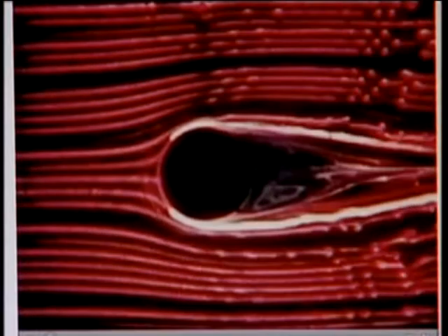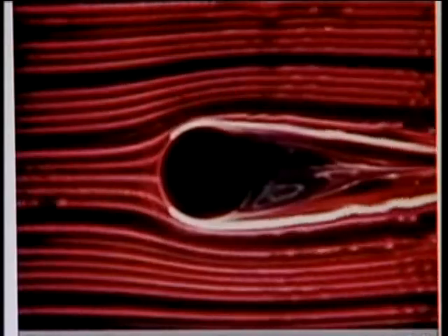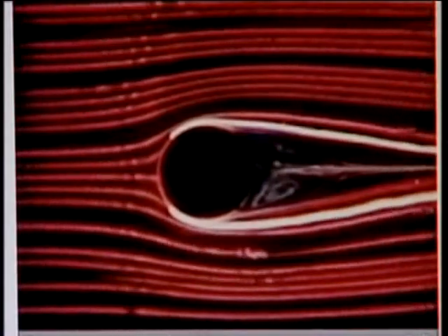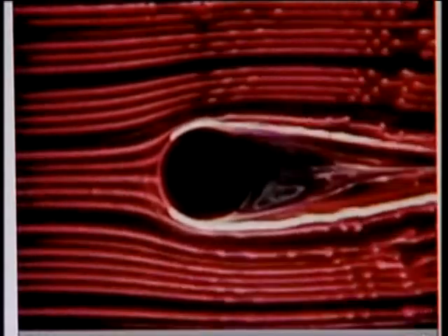Because of this, we can analyze this phenomena, and if we can suppress the separation of the fluid particles which is happening here in this case, then we can offer less resistance by the fluid on this cylinder, right. So that's why you might have seen the dimples on the golf ball.